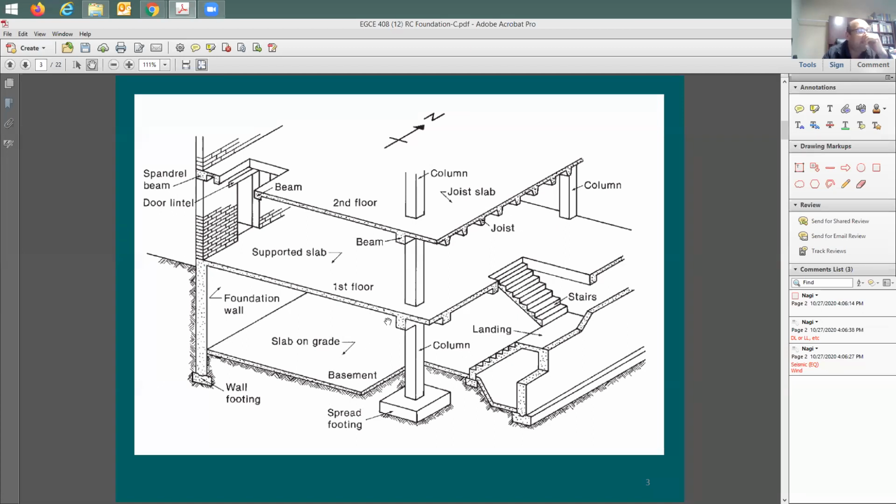Now here you take the load from the entire slab and then you concentrate it in a column. So now the load is going to be inside the column. Which means if you compare the load that goes between the slab on grade and the soil per square foot, to what you have on the column per square foot of the cross-sectional area of the column, the former is going to be extremely low compared to the force on the column.